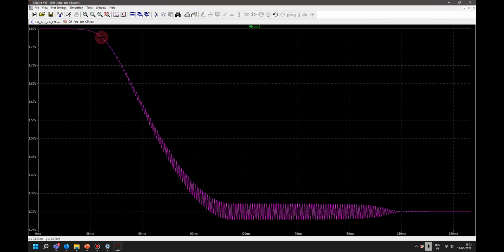Then as the common mode input voltage is increasing, current starts flowing, and in this region, current of ID by 2 will be flowing, and hence you are getting a good gain here. And again, if you keep increasing, the transistor will come out of saturation, and the gain is decreasing. So is this graph understood?